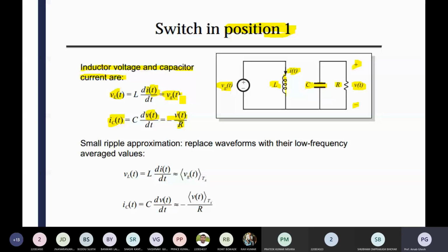So at time equals 1 second, you will get some of the inductor current value and some of the capacitor voltage value as time changes. So you can plot some diagram where your R is changing and time is also changing with regular intervals. For each individual instant, you fetch the value of inductor current and capacitor voltage and plot them with respect to the changing resistance. Okay, that is your assignment. So next week you can show me those results, so I can check it.